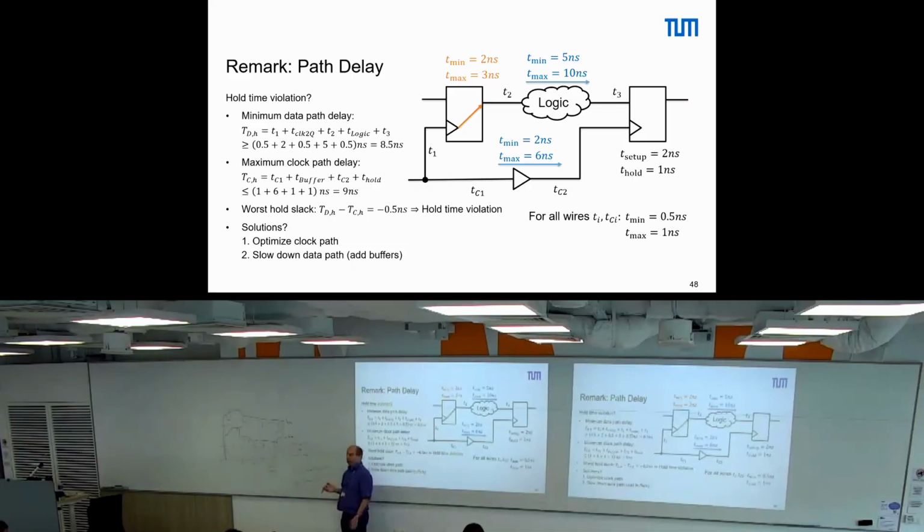The purpose of such a register is, for instance, very commonly used: you have a serial input, where one bit after the other comes in. With each clock cycle, you shift this in, and at the end, you have some parallel structure out, where you have 8 bits output in parallel. So actually, a deserializer. Yeah?